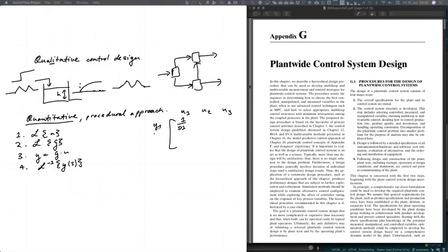So we have a set of outputs and so on, and we can have maybe y2, y1, u1, lots of different inputs, and we can have a full set of inputs here, and then we can do a procedure like the RGA, and the RGA can give us guidelines like, you know, if the RGA looks like ones, that's a good pairing, right? So now we have systematized the process of figuring out control couplings.